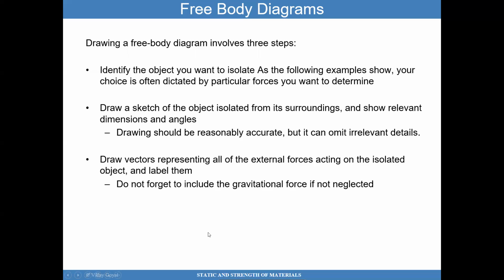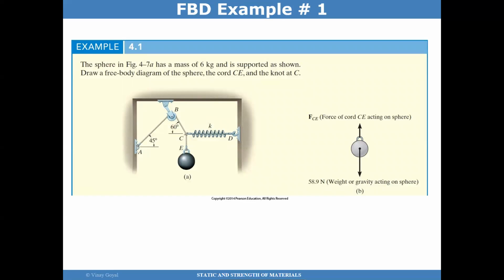Draw vectors representing all the external forces acting on the isolated object, and then you want to label them. And don't forget to include weight or the gravitational force, because in many cases that drives the problem. The best way to illustrate this is through various examples.